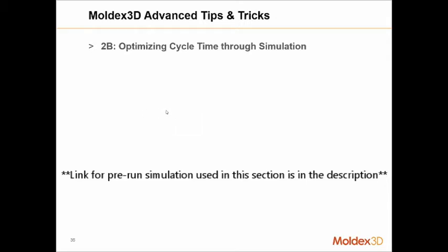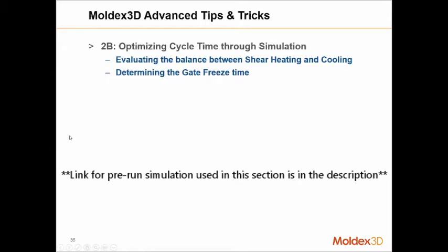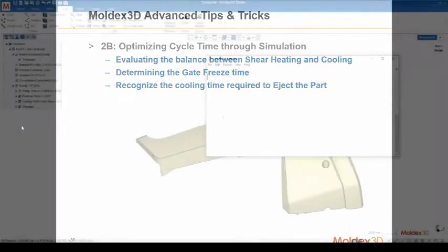In this lesson, you can expect to learn about evaluating the balance between shear heating and cooling, determine the gate freeze time in your packing stage, and recognize the cooling time required to eject the part from the mold.